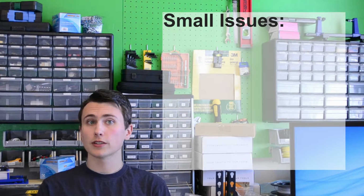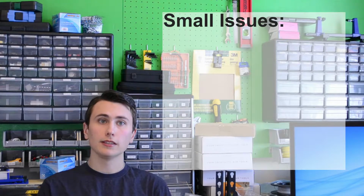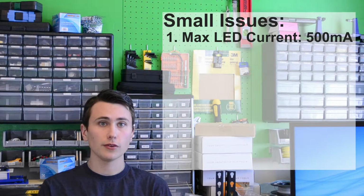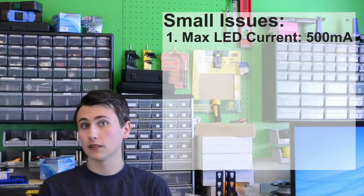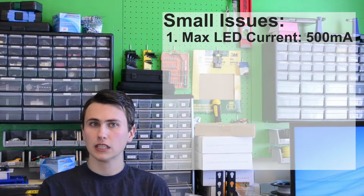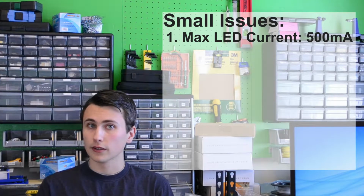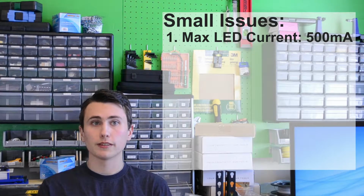In the first iteration of the design, the maximum LED current was set to 500 milliamps instead of 330. This is fine, sort of. Some of the LEDs can handle this peak current, but others are only rated to handle 350 milliamps maximum.